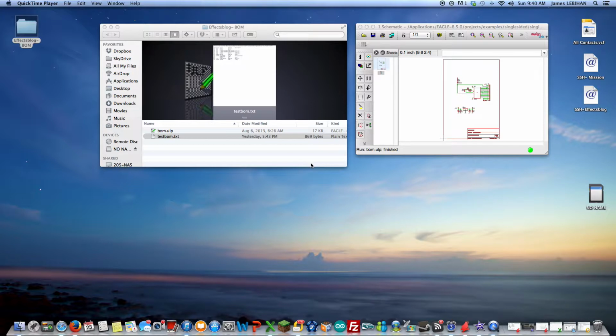You could do this manually just by writing them into a spreadsheet, but if you're using a PCB design tool, quite often those have the ability to export the components as a BOM. So that's what we're going to get started with here. And I'm using Eagle here, and I've just opened one of the example projects that comes as default with Eagle, just so that we can see how it creates a BOM.